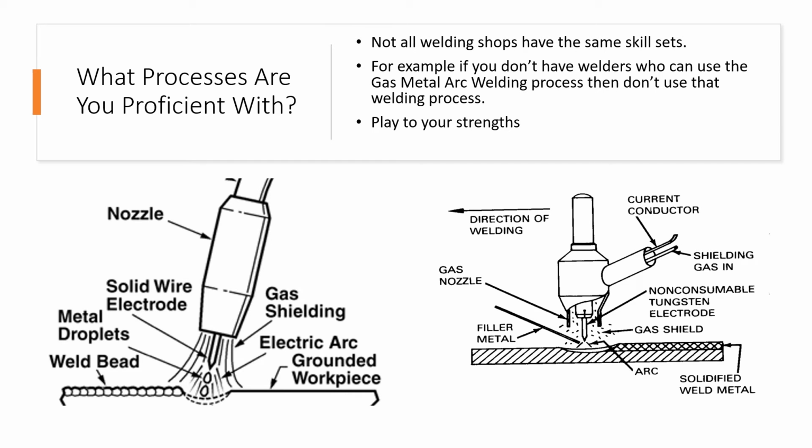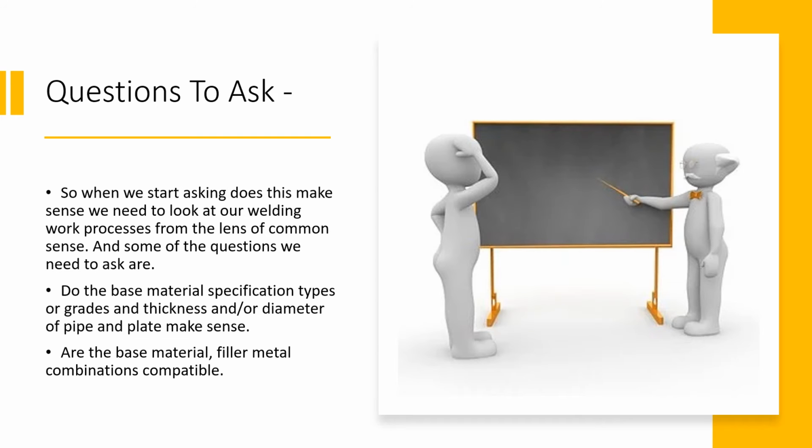So most shops, in my experience, have one or two welding processes that they're really good with. So, my general idea is play to your strengths unless you are forced to do otherwise. Whatever you do proficiently, kind of stick with that. And if you got to venture outside of that one, okay, do it, but do a little research and get everything put together correctly. So anytime you're doing a pWPS, there's some questions you need to ask yourself when you're putting together your